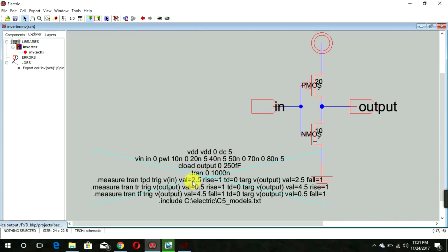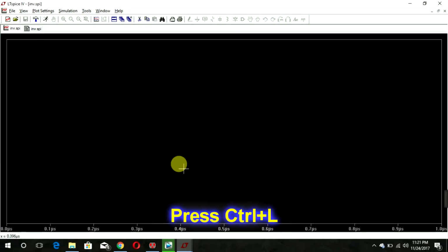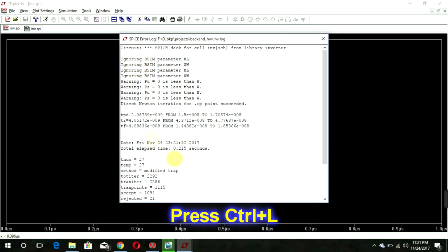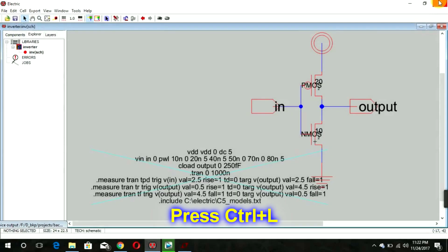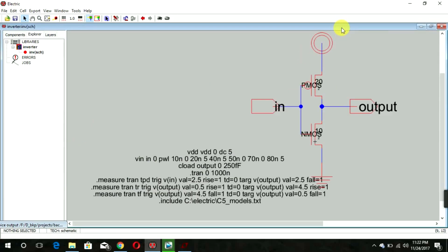If you have any problem understanding the statement, where we have to use which node and rise and fall, just comment below or write me an email, I'll be there. So this is our propagation delay, it's around 2 nanoseconds. That's great. Now we just have to change the capacitor and see how our delay is affected by the capacitors.